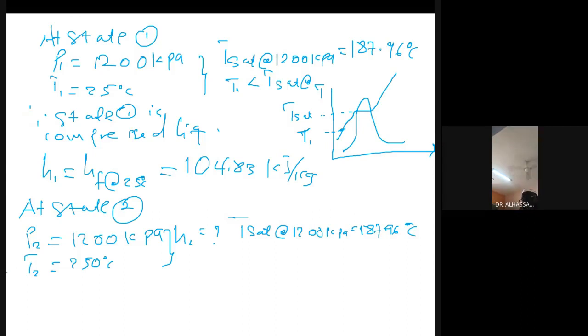So now what is your conclusion? Superheated, because T2 is greater than T saturation, which implies superheated fluid.